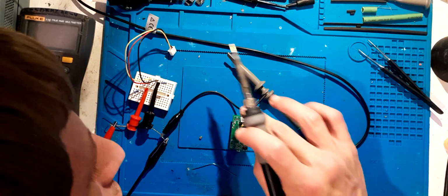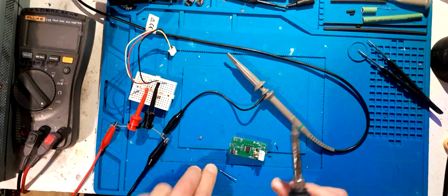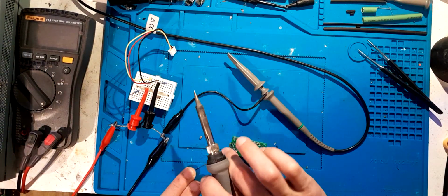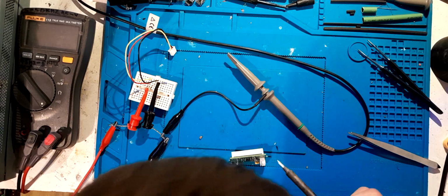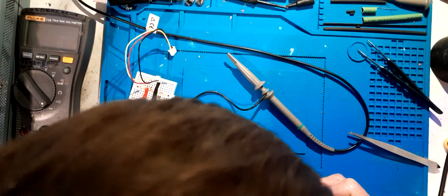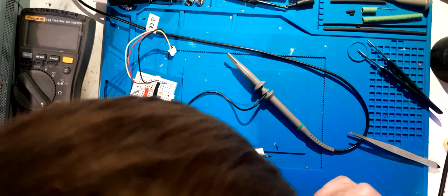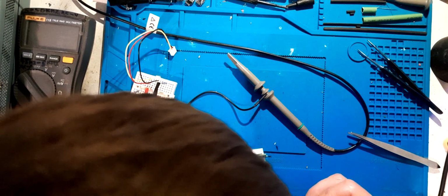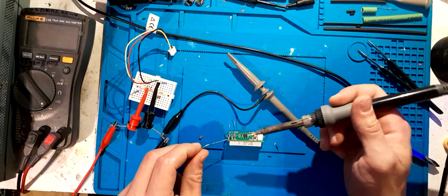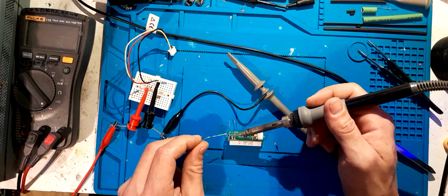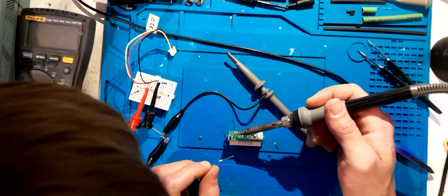It's not exactly the same as a supercapacitor, but I mean, you could theoretically build a super cap out of a whole load of small capacitors that've got low ESR and then hook them together to form a capacitor that just wants to charge and discharge almost instantaneously, but it'd be a pretty strange waste of time.